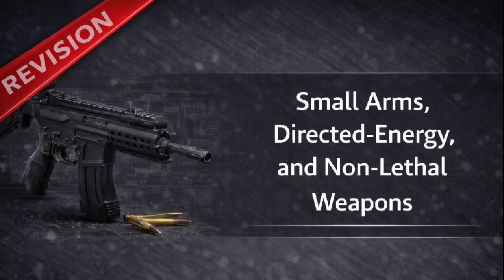So if we compare all three operating systems, blowback, recoil, and gas, what is the single biggest operational advantage that gas operation holds over the other two? Its adaptability is simply unmatched. Gas operation is the only system that can genuinely and reliably regulate the power available. Through the gas regulator. Exactly. Engineers incorporate a gas regulator that allows the operator to control the flow of gas to the piston. This is essential for compensating for variables like heavy fouling, extreme cold or heat, or variances in ammunition quality. It ensures dependable operation in conditions that would just stop the other systems.